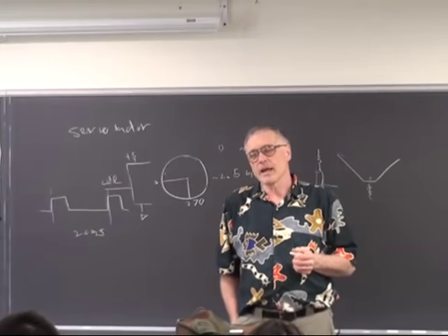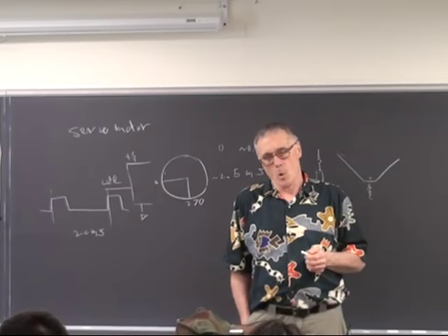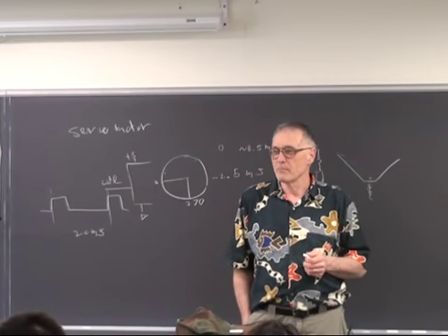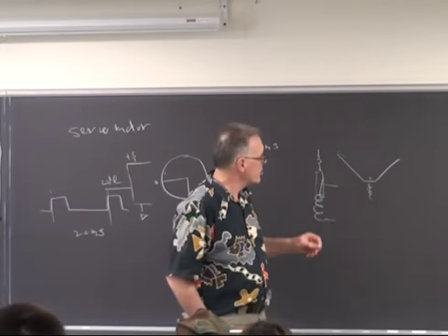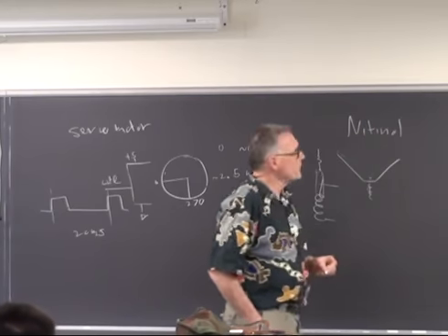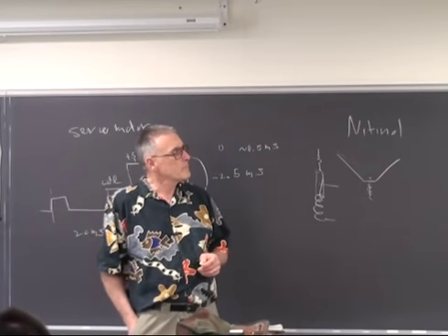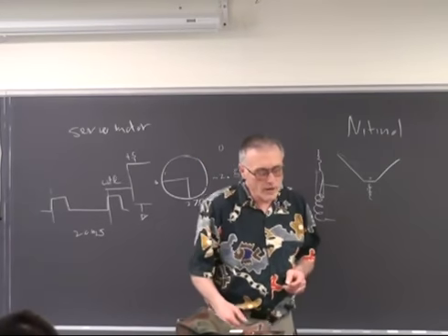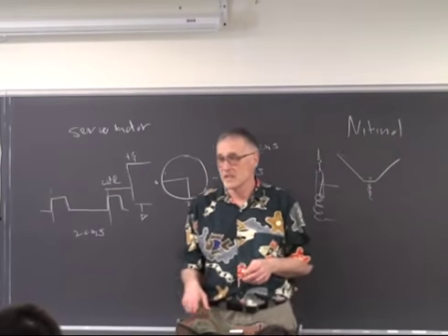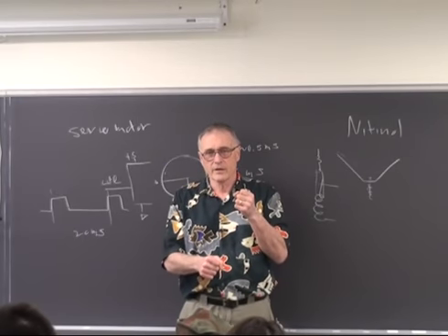There's a very interesting actuator I've seen used a few times in this lab. It's very slow, typically a second. It's a memory alloy called nitinol wire. Nitinol, nickel titanium, I think. It has the interesting property that when you put enough current through it to heat it to 50 degrees C or so, it shrinks by 2 to 5%.